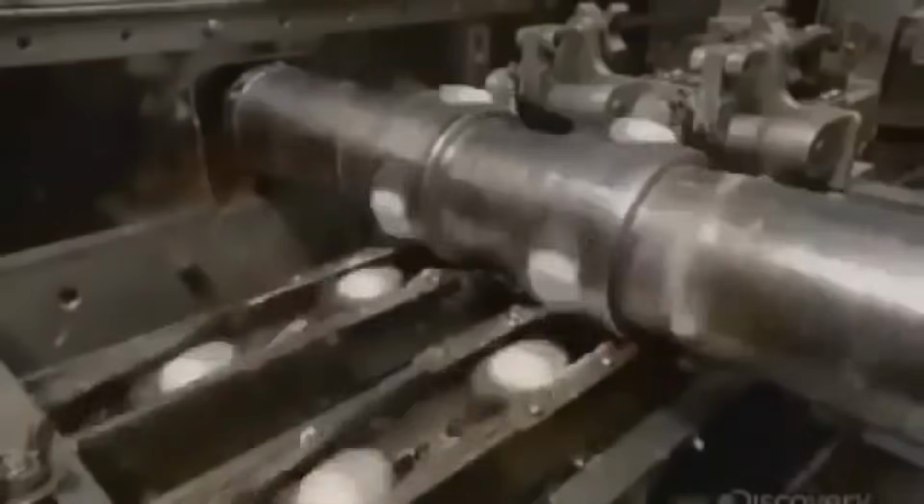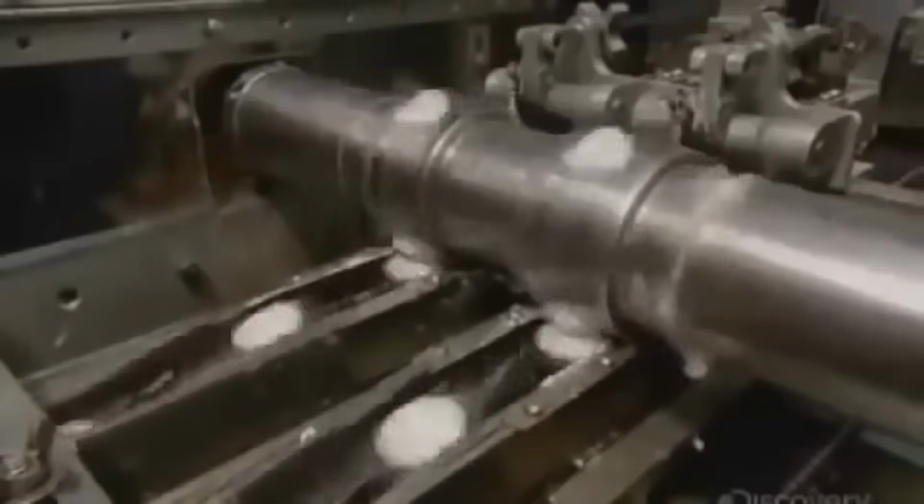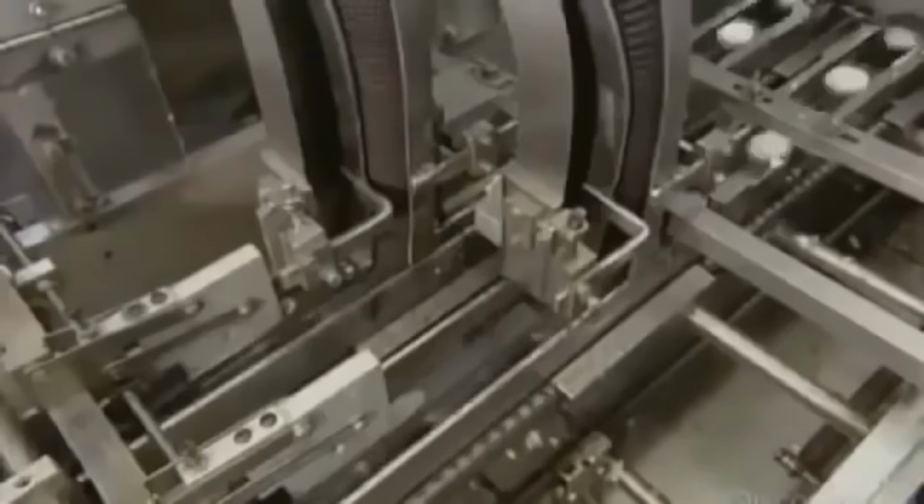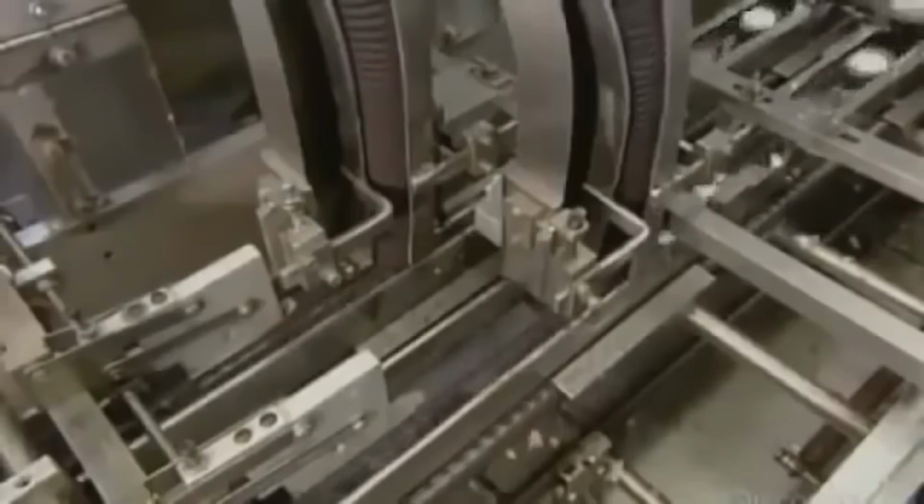For Oreo wafers, the final sheet is quite thin, often around 3 to 4 millimeters, with a consistent density and moisture distribution. Getting this thickness right is critical. If the sheet is too thick, the cookie may not bake evenly or could become too brittle. Too thin, and the cookies may crack, burn, or crumble during sandwiching.